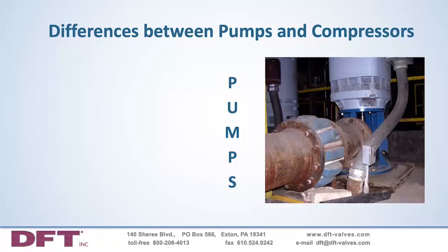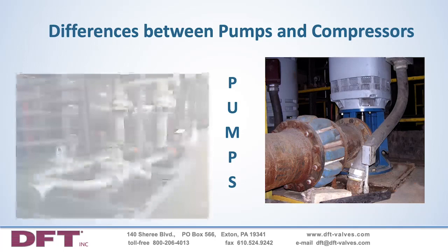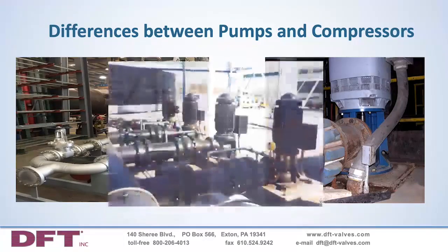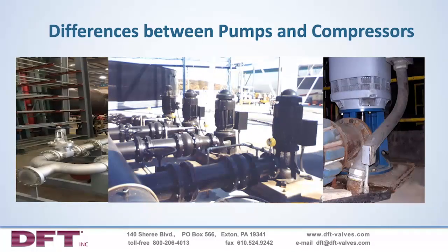Although the terms pumps and compressors are sometimes used interchangeably, there are distinct differences between them. A pump is a machine that moves a liquid, which could also be a slurry, from one point to another via some type of mechanical action. A pumping mechanism, either centrifugal or reciprocating, imparts energy to the fluid, thereby forcing it through the pump outlet.